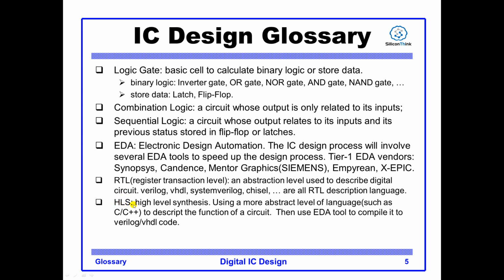High-level synthesis, HLS. This means you can use a more abstract level of language to describe the function of the circuit. Usually high-level synthesis code is at a higher abstraction level than RTL. So after you have coded high-level synthesis code, you have to use EDA tools to compile it to RTL level code, such as Verilog code.